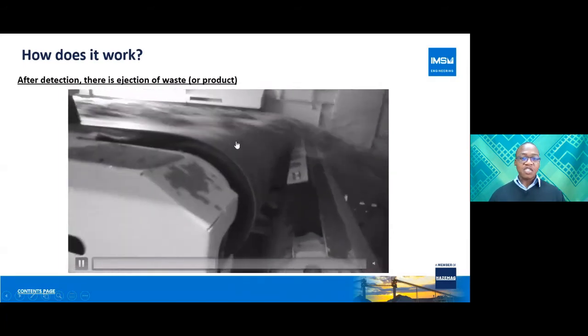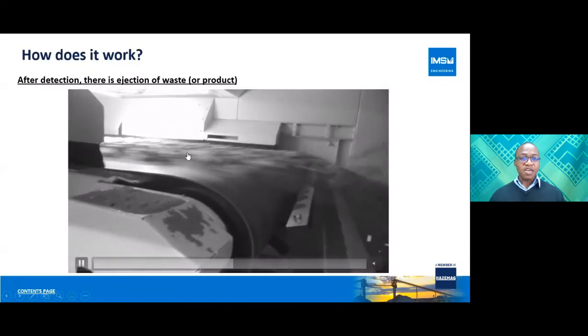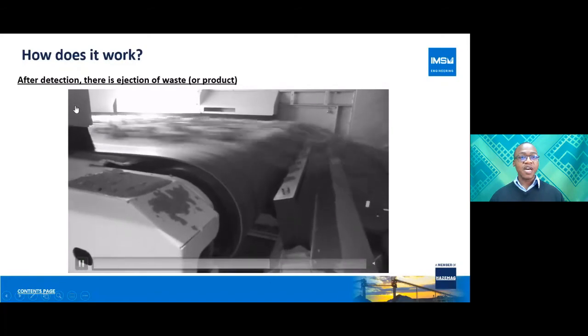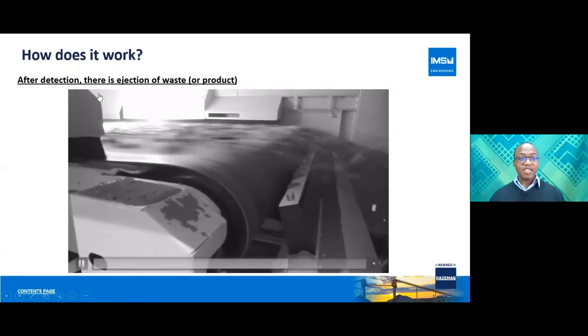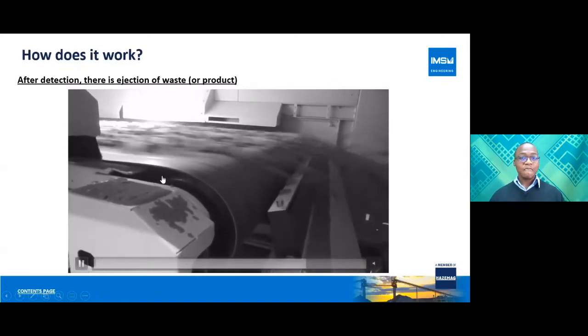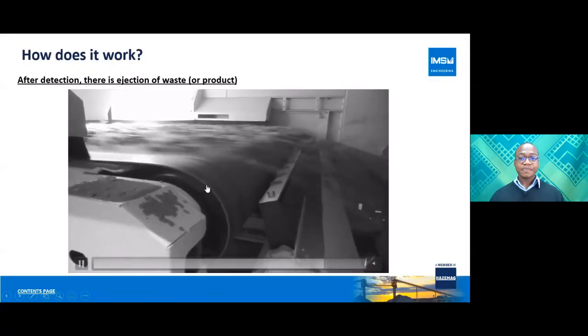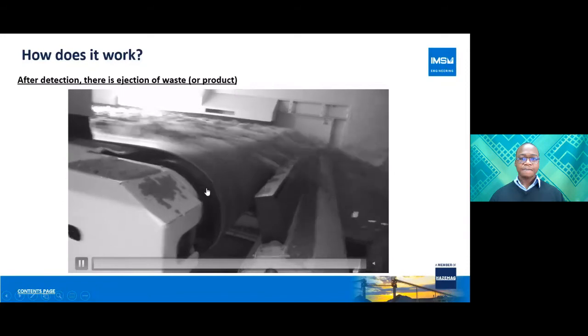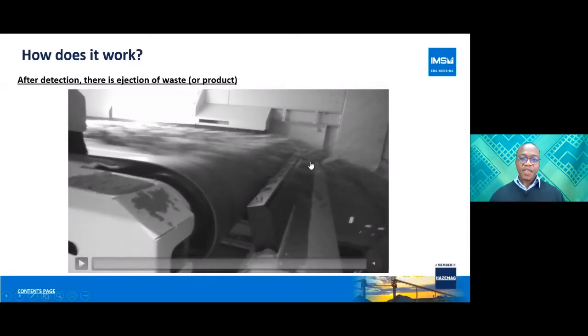As you can see, the material on the conveyor belt is in a monolayer, and your sensor is typically located behind here where you see the light. And that's your valve bank. Essentially, material coming off the conveyor, your waste particles, are being shot and they then follow an upward trajectory.